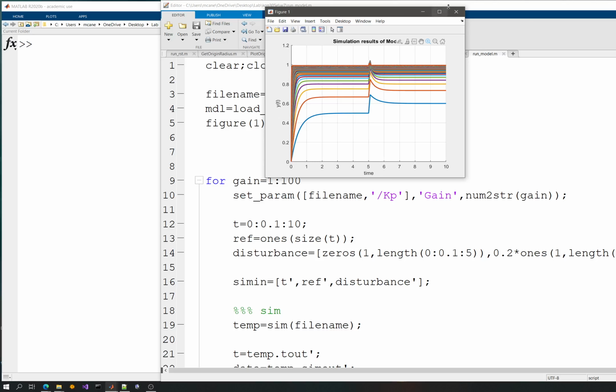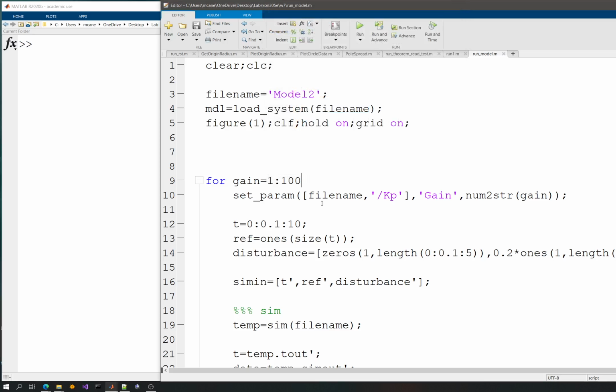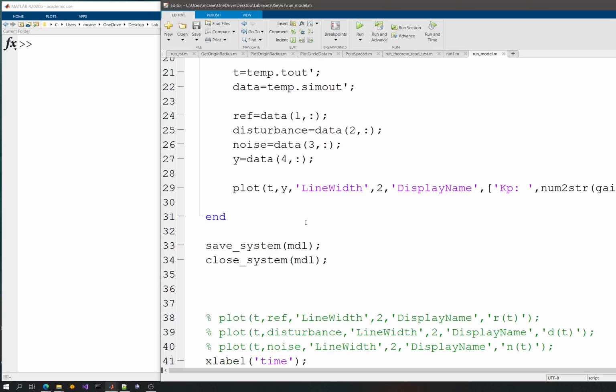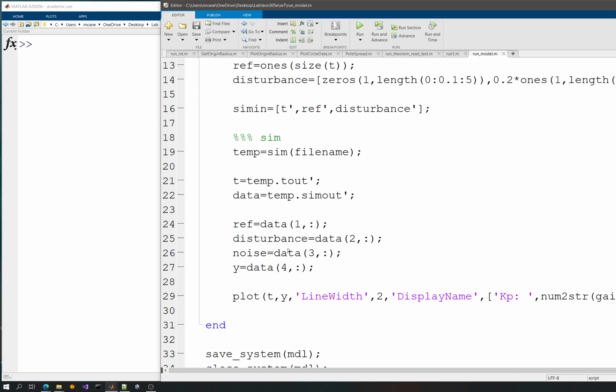Now we have seen that we can use a Simulink model, so that we can code a wrapper that uses the Simulink model in the background and generates our results. We can use the workspace for interchanging variables. We can use files, and it is also possible to just use files and use a mux, demux to arrange it so that we can access all the data via code.